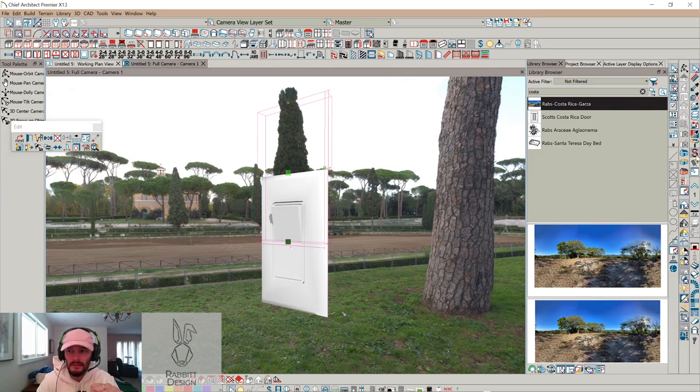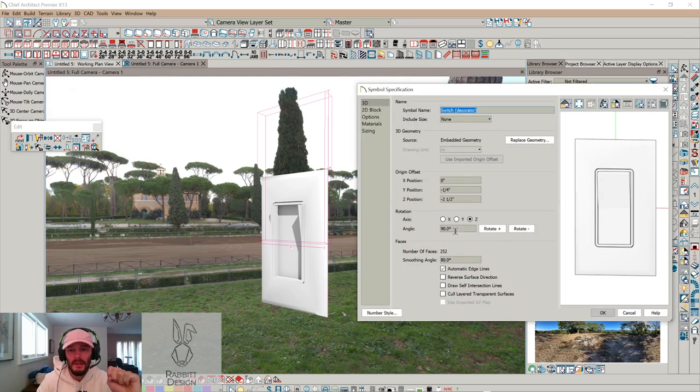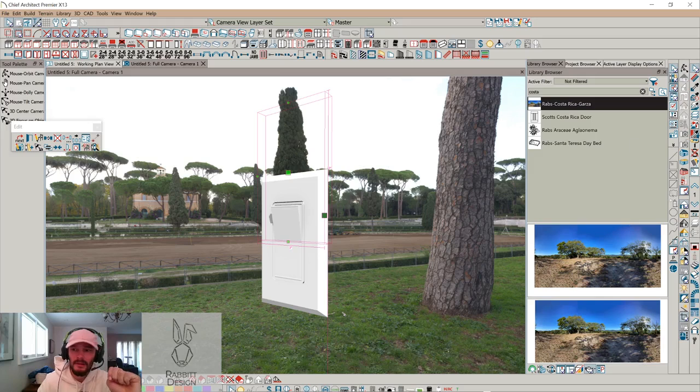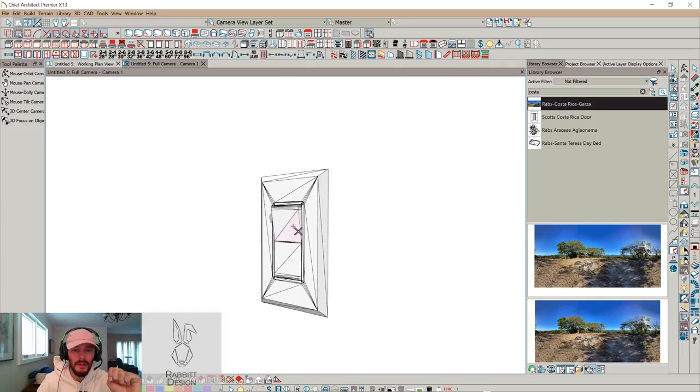and I use the delete surface tool, what's going to happen when I click on this? It's going to get the face of that rocker, right? That's what it did. Now let's go back a step. Let's open it up again. If I designate this smoothing angle as 0, and I use the delete surface tool, look what it gets. It only gets a couple of these vectors. It's going to be really obvious if we change our rendering mode to a vector rendering mode, right? Then it shows exactly what we're deleting, right? We're highlighting these individual faces.